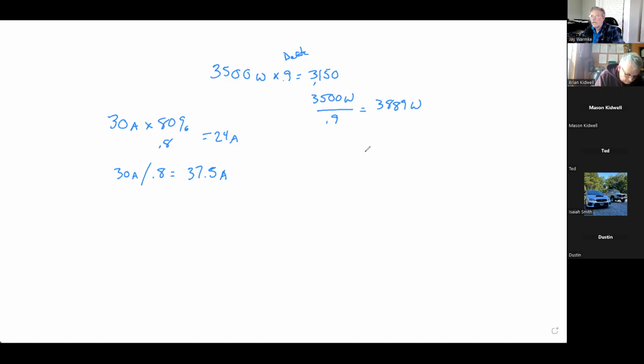Okay, and related to ampacity, also in that same quiz, I could not find it in the text. I could have just missed it, and I could not get to the NEC section in one of the earlier chapters. But you introduced an NEC safety factor of 1.25 and a solar variability factor of 1.25, which were multiplied times whatever the amperage was for any of the wires.